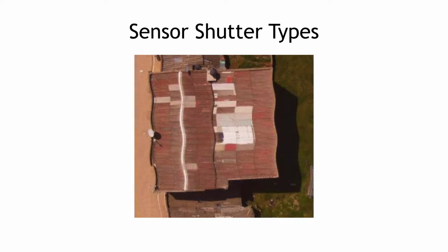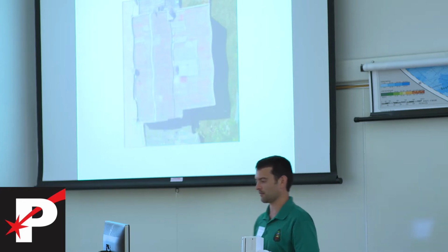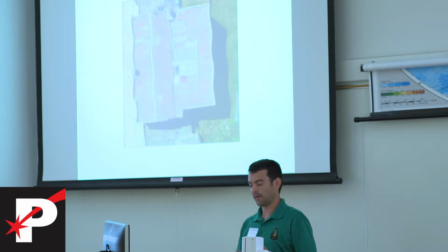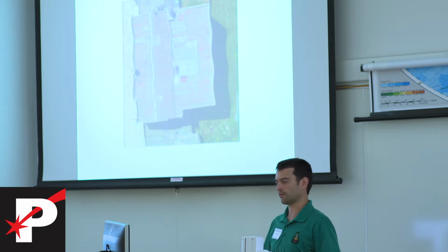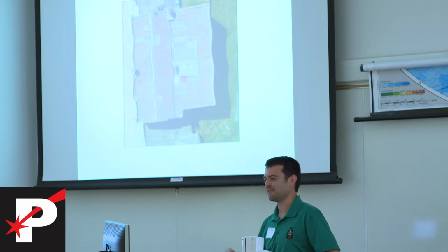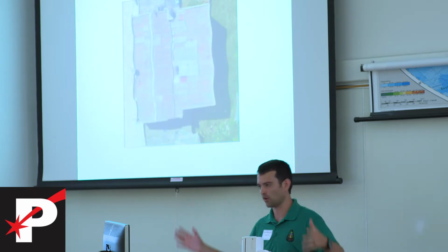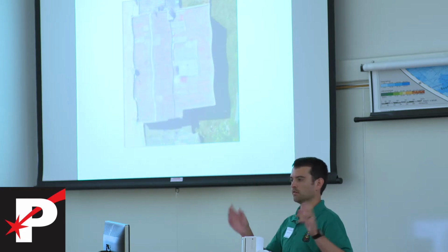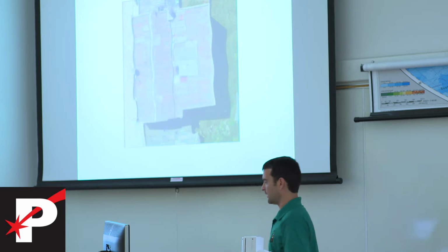But essentially this is not good for stitching, for photogrammetry. Not only does it not represent what you're actually trying to shoot, but it also is difficult to do tie points in your stitching software. So a lot of times, if you do have this issue, you need to balance your props, please, which is one of the biggest things with the toys, the lower economical platforms. Nobody balances their props. It's like, hello, vibration. But most of the gimbals these days, for the cameras built onto the drones, do not have this issue because they've tuned them so well. It's more for a lot of our customers that want to strap our little survey cameras to a drone or whatever, and they don't properly isolate it from the vibrations of the motors, so then the vibrations get to it.